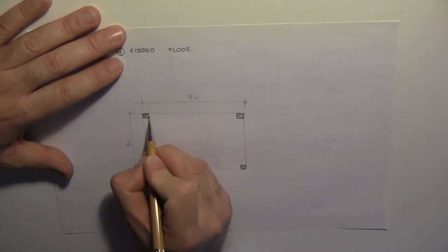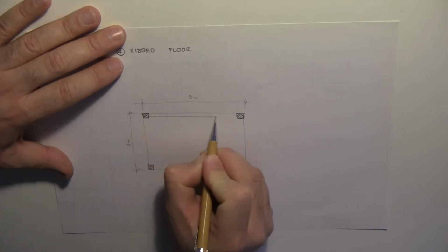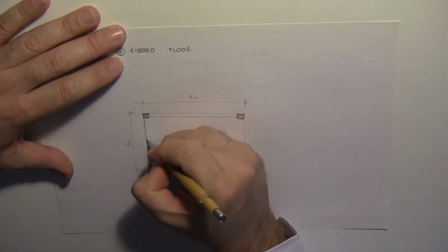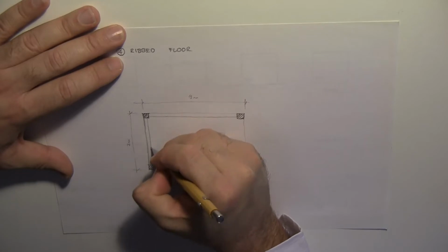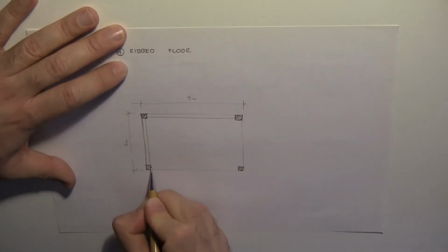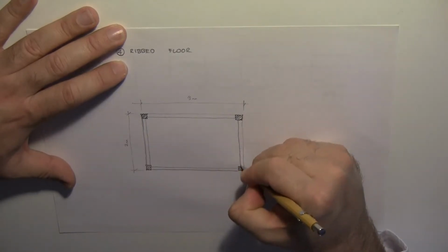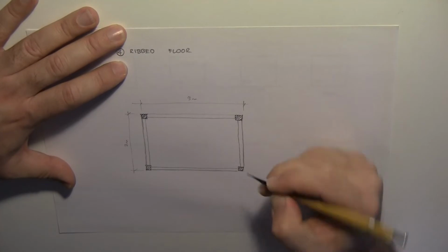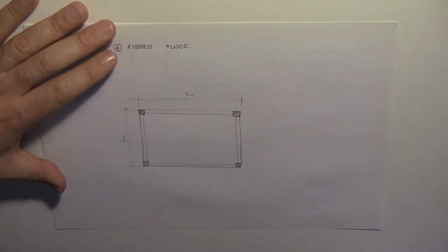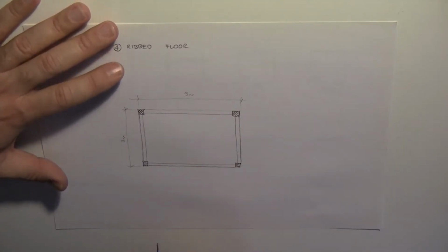What we will do is we are going to tie the columns to each other like we tie the columns to each other in slab floors. This time, as the span is too much, we do not want to lose the moment of inertia of our beams. We place them vertical, not flat beams like we have in hollow slab floors.